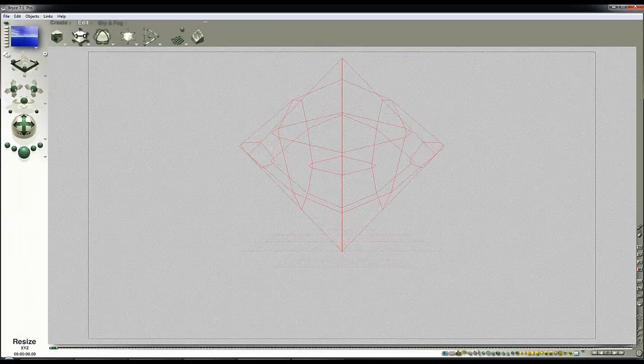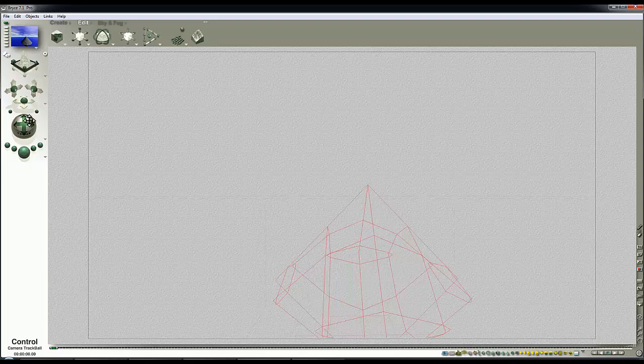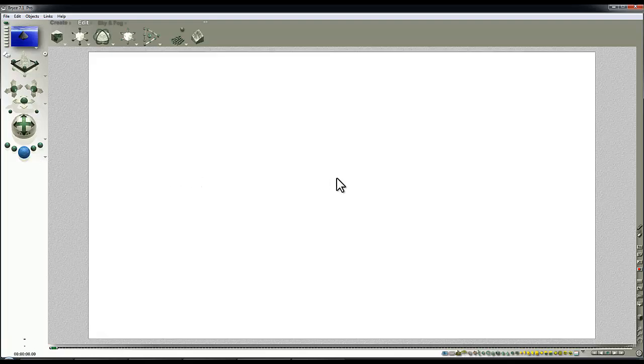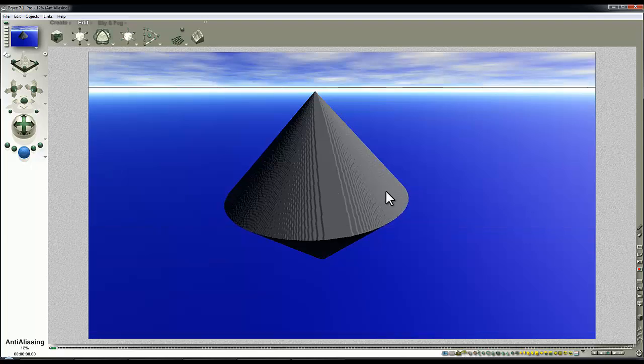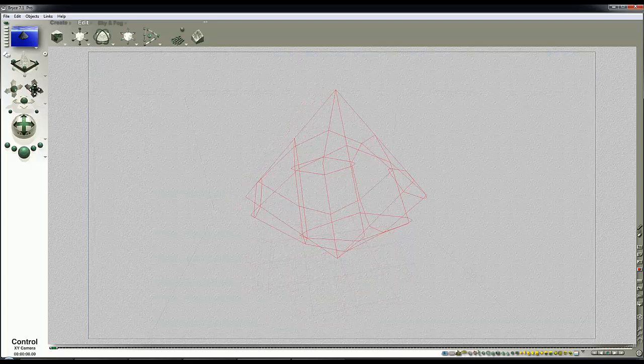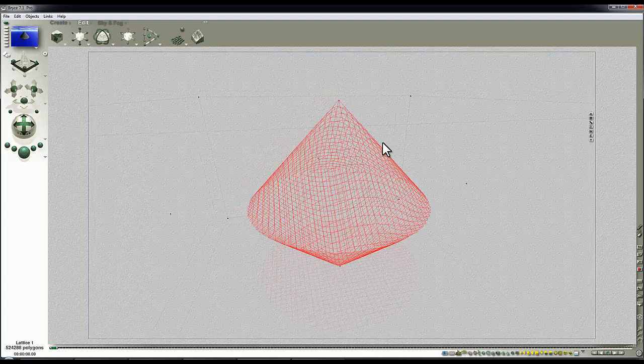I'm going to enlarge it a bit so I've got a better view. Lift my camera up and point it down. So I think the blob maker works only at 8-bit, and the height maps in Bryce are 16-bit, so it's come out with this slightly jaggedy appearance. But don't worry about that, that's a different issue and sort of beyond the scope of what I want to look at here. I need to create a material on this that's distinctive so that I can show you what's going on with the materials. But it works whatever, and that's the point really. Once you've solved the problem once, you know how to solve the problem.